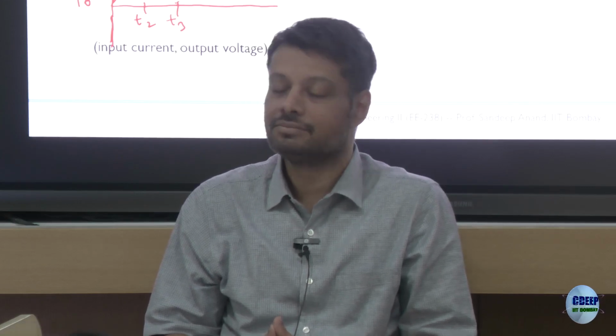But how do you know? Maybe you have positive, maybe you don't have positive, right? How do you know? Because the inductor will resist trying to make it negative. Okay. And at T3, L di/dt, we already assume di_o/dt is negative. Yeah. And that's how we converge to i_o being 0. Okay. So di_o/dt is negative, so it will obviously be reducing.